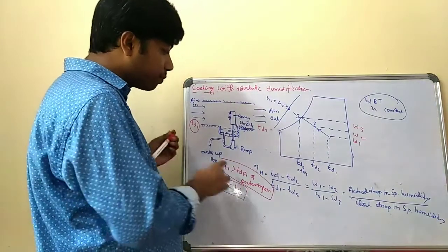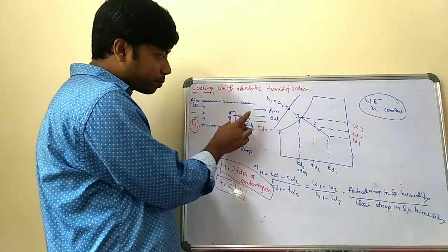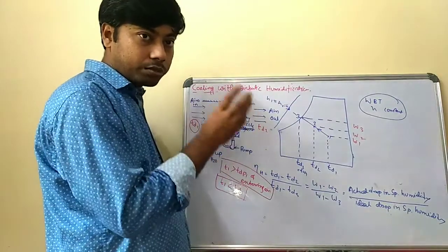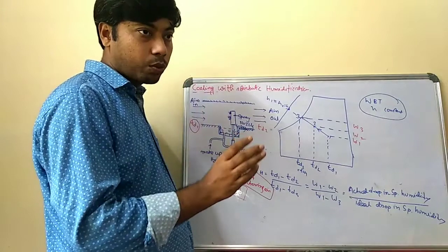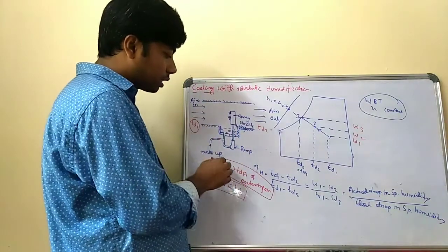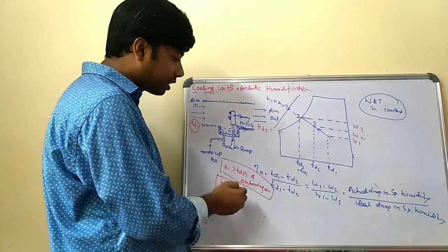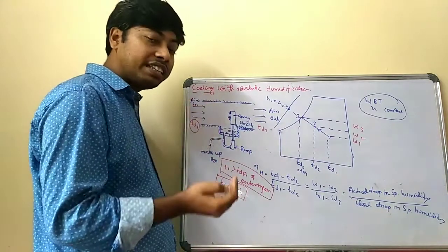In this arrangement, the temperature of the spray water through the spray nozzle should be greater than the dew point temperature of the entering air.